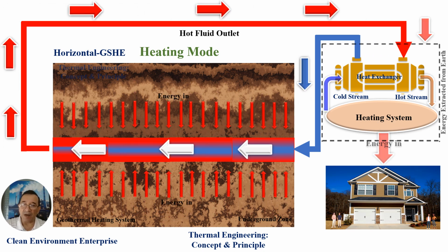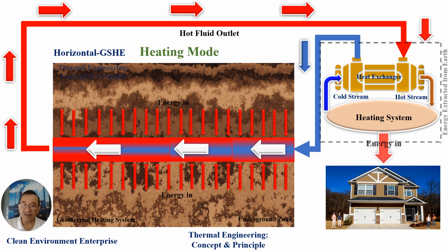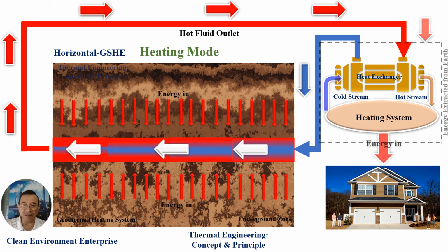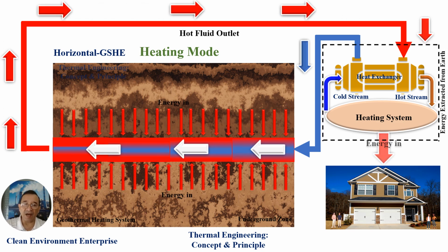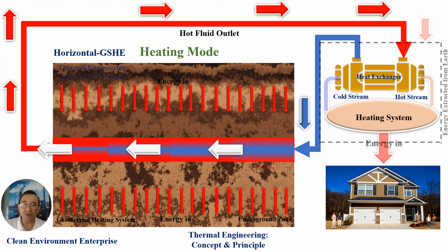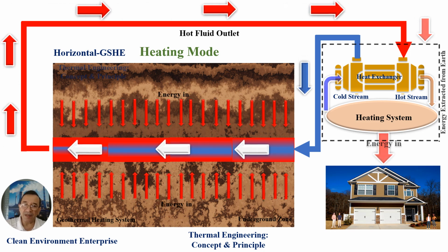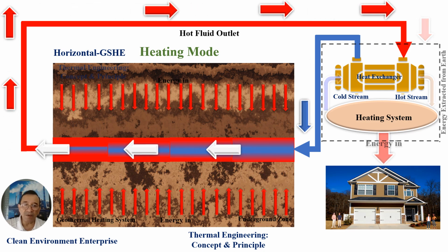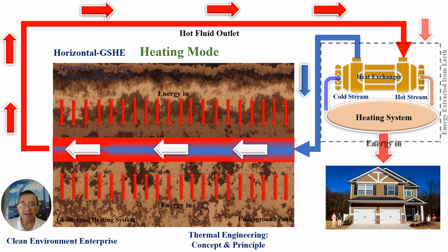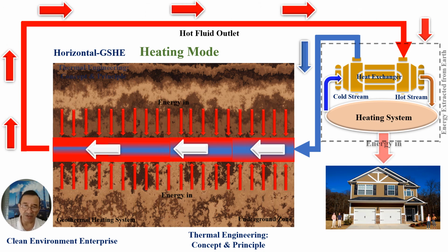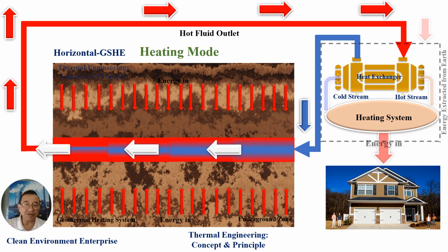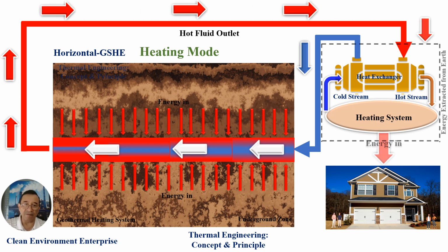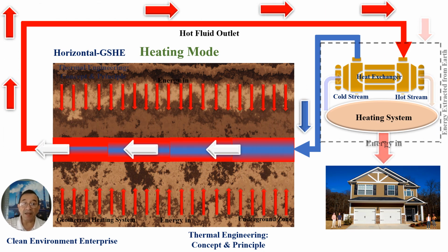Although we are talking about a low pressure range for the fluid passing through these pipes, again, they can handle high pressure. Usually the pressure may be between 2 and 3 bars for the fluid, which is usually liquid, pumped through these heat exchangers. And the heat exchanger is made of a configuration of slinky pipe.